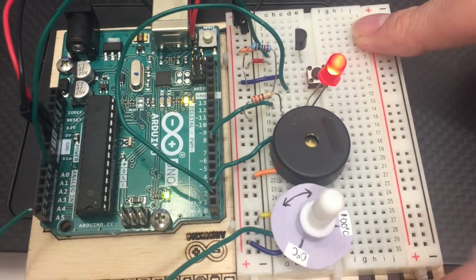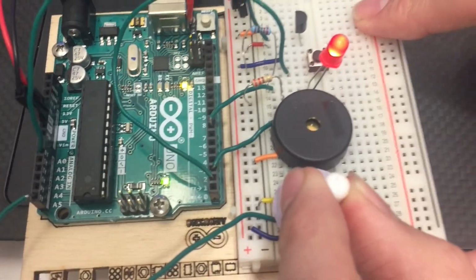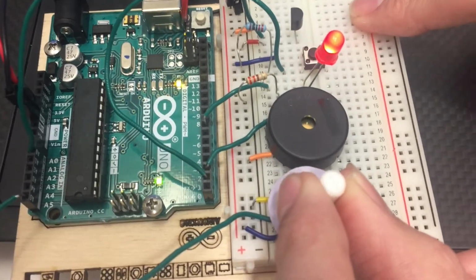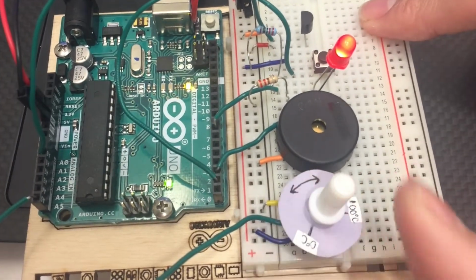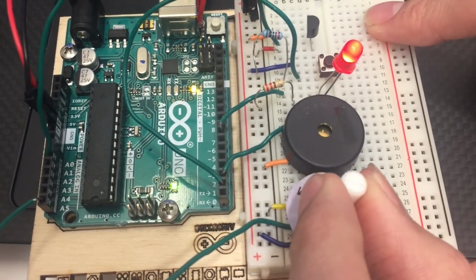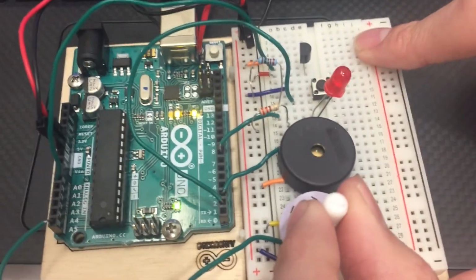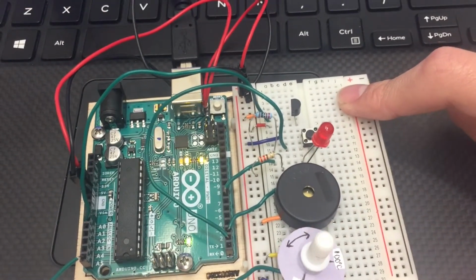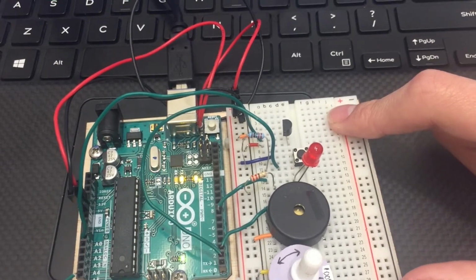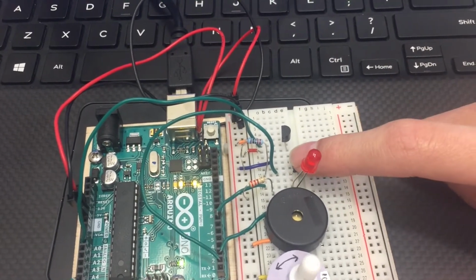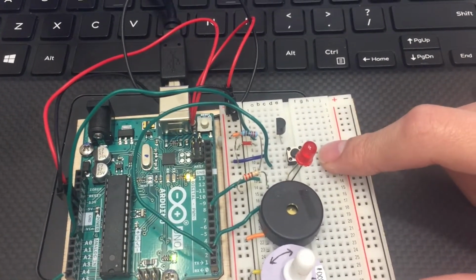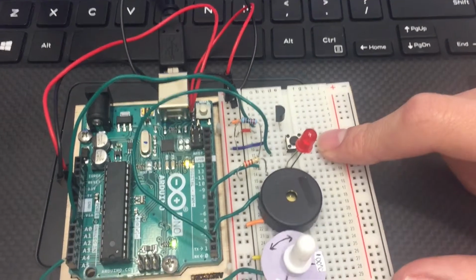As for outputs, the piezo emits a beeping alarm and the LED flashes when the surrounding temperature is greater than the threshold temperature and the bacteria is not growing at an optimal rate. After the push button is pressed and the alarm and the LED are stopped, the reset button is used to re-enable the alarm.